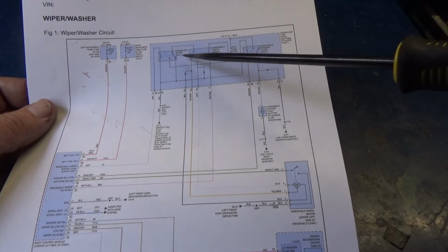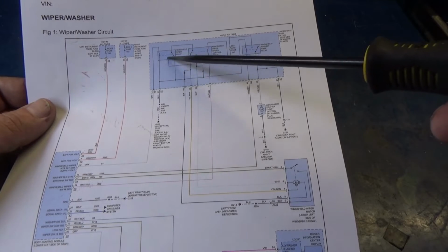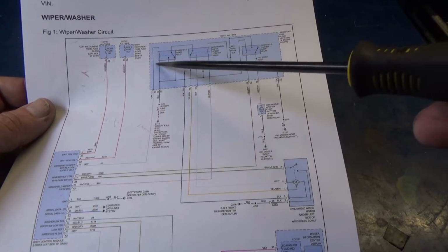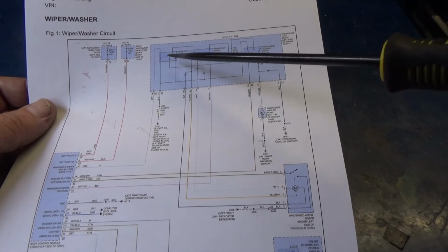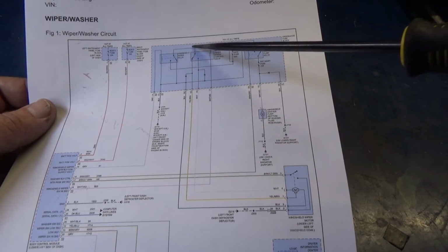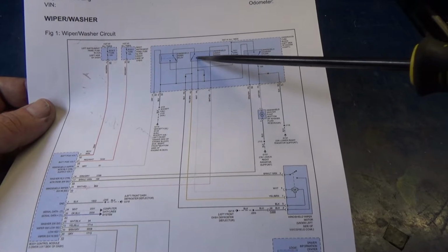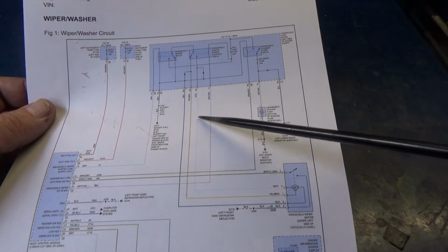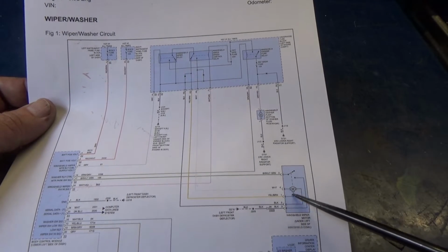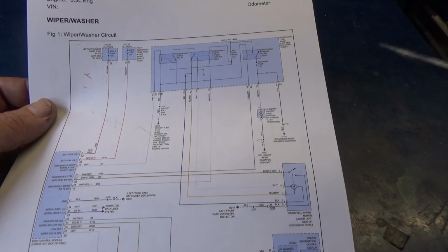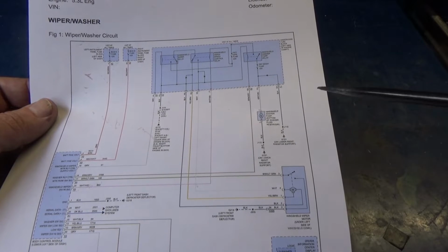Now you're going to put power. Remember, these are still slammed over because this relay is on or energized in any position other than off. So you've got power coming over here. Now you've got power coming down on this set of contacts, going down to the white wire, bam, to the high speed windings on the motor, and then you've got your high speed.